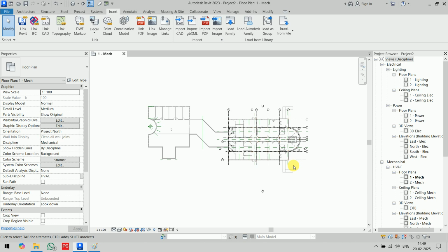But if you click on the center of the face, you cannot select any type of object with the help of face if this is disabled. Now you can enable it, so you can easily select by clicking anywhere on the face. These are the selection filters. If there are 3-4 faces overlaid and I enable this one, I will just click and it will be easier.